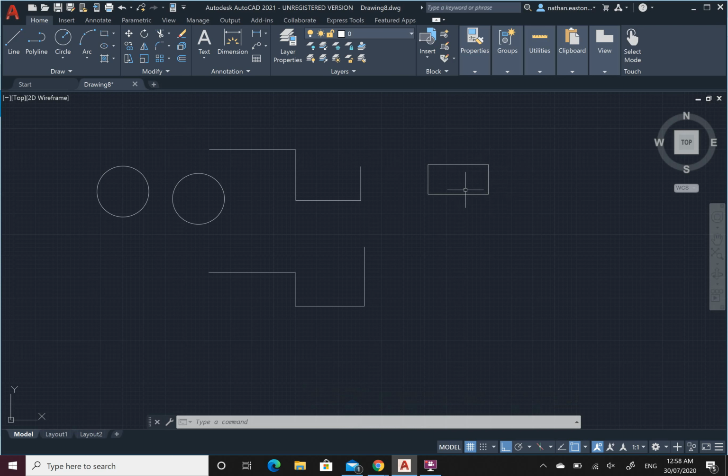Okay, now if I want to move this shape, I'll select it. So I'll use the green, and the move function is this one. So I select what I want to move, click move. Now what this is doing is CAD is asking you to specify a base point. This is a reference point on where to move from. As we become a bit more proficient in drawings, this will become easier and make more sense.